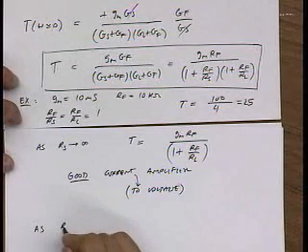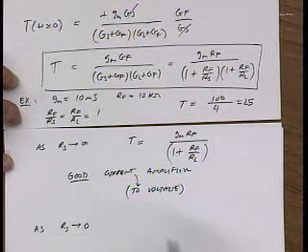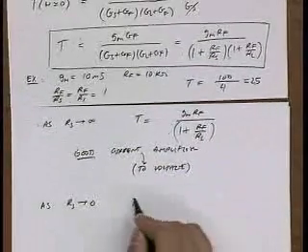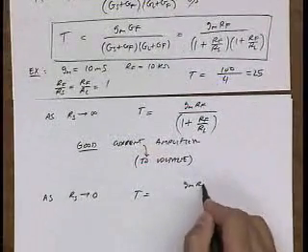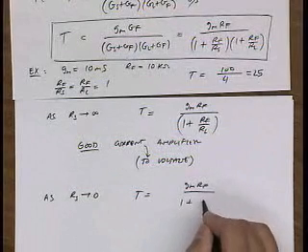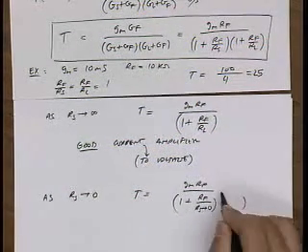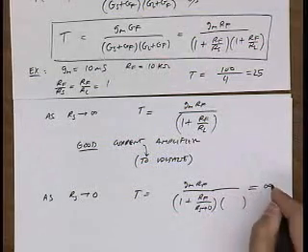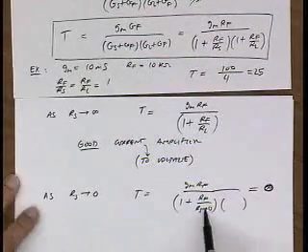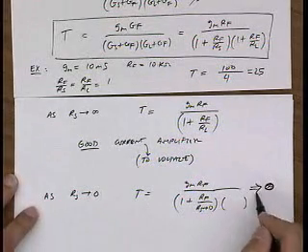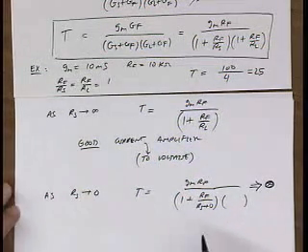On the other hand, if we try to use this as a voltage input amplifier with very low source impedance, then the loop gain goes to GM RF times 1 over RF over RS, with RS approaching 0, which basically goes to 0. This term becomes very large, and the ratio becomes very small, and so there's no loop gain.